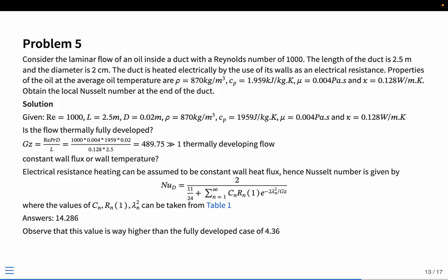So all of this is to again emphasize things. The gate or the checking criteria is your Graetz number, which you compute and see whether that value is very much greater than 1 or not. Ideally, 1 is not a correct value, even if it is sometimes close to say 5 or something, then 1 by z will be around 0.2, and even in that case, your Nusselt number will actually be very close to 4.36. This need not be exactly 1, it can be a little higher.